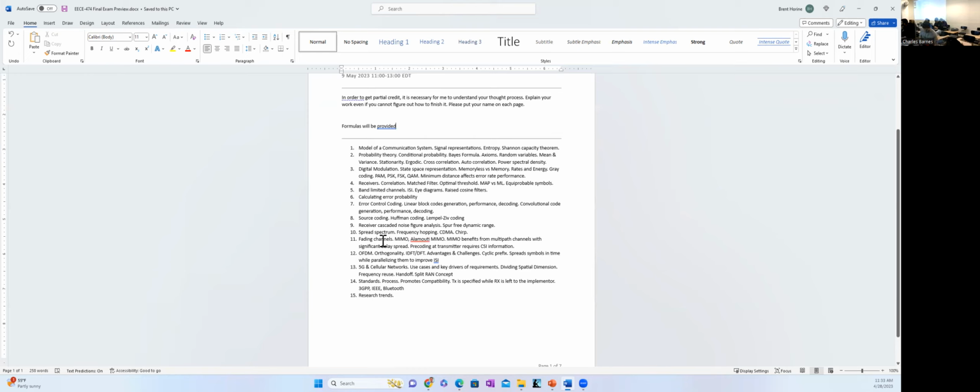If you've just got a line of sight and no reflections, MIMO's not going to do a whole lot for you. We can do linear combining at the receiver, and we can also do pre-coding at the transmitter, but that requires us to be able to send channel state information somehow to the transmitter.